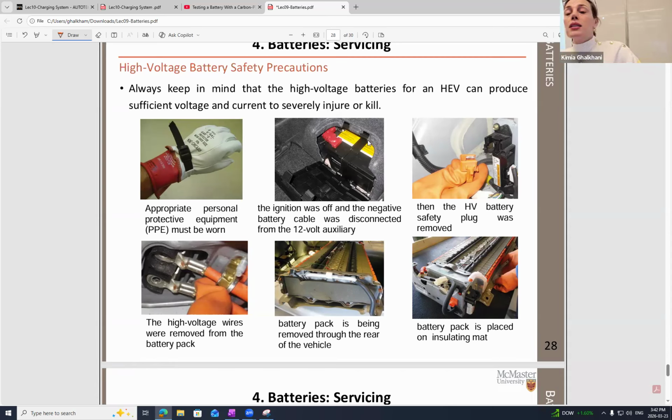The very first important thing is that the battery may release some toxic material. That's super important. And definitely high voltage is also there. So you have two types of danger. But in a situation where the battery is disconnected, you are not dealing with the voltage part of it. Still, there may be leakage, because we troubleshoot when we feel there is trouble. What if that trouble is that some of the actual chemical is out of the battery, or the battery has a leakage? Then it might be on the surface. You don't want to touch it.